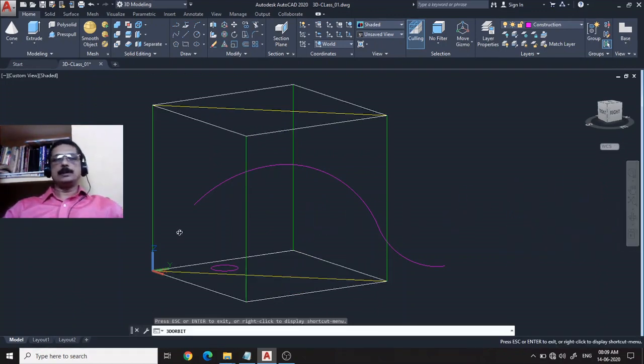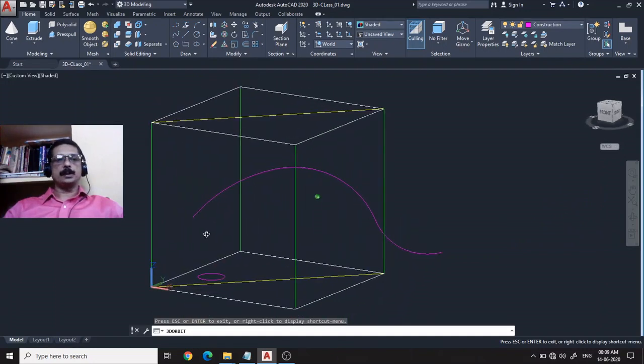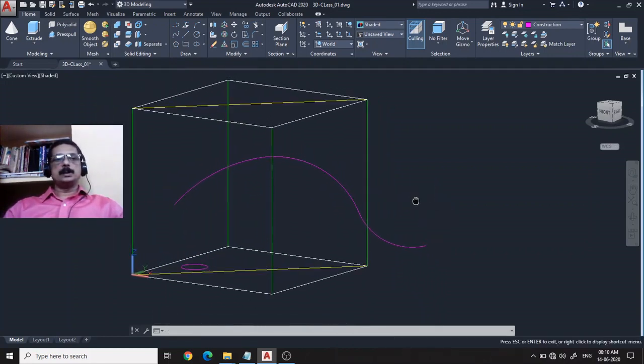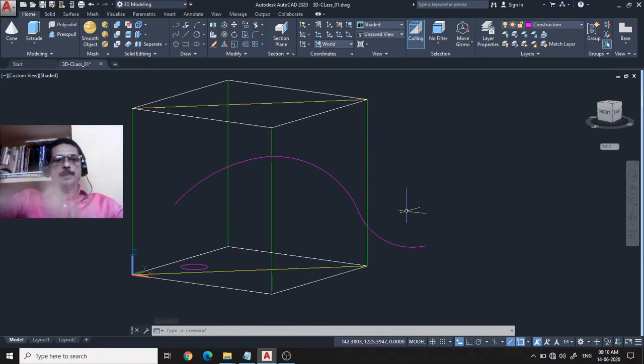Now we'll see another interesting command which is called press pull, by which you can create solid models very easily. Okay, so in this case also we need a basic drawing in 2D, which can be pulled to create some object, or pressed to remove some object. So I will demonstrate that one. See, the press pull command is here, or you can type press pull. For demonstrating that, I'll be drawing something here.